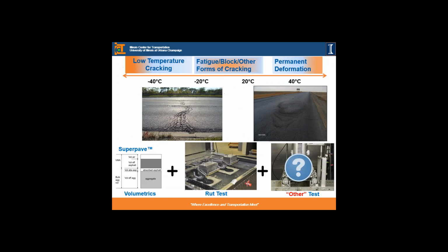So that's why the discussions right now are around how do we really solve problems, or at least evaluate the problems that may be coming from the usage of high recycled materials. So with the current specs and mix performance, we are trying to really eliminate the problems at low temperature associated with thermal cracking, intermediate temperature fatigue, block, and other forms of cracking, and permanent deformation